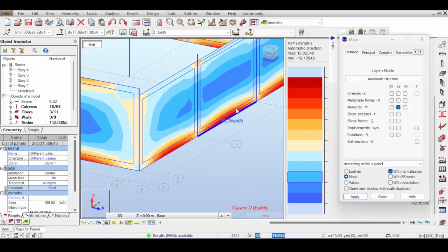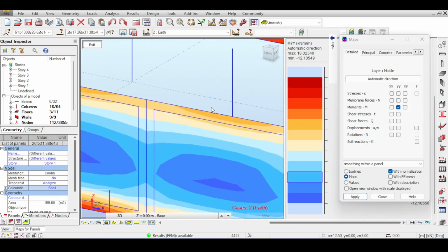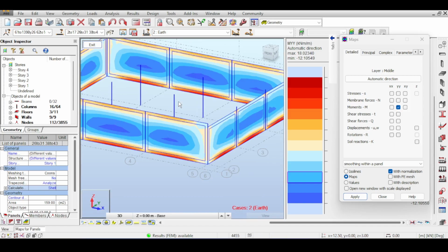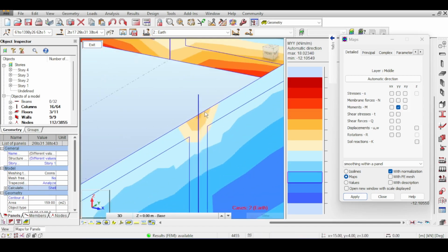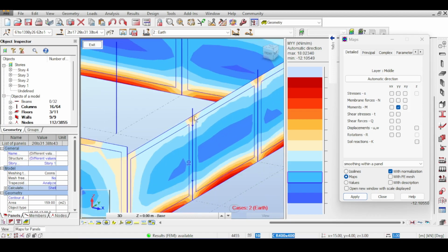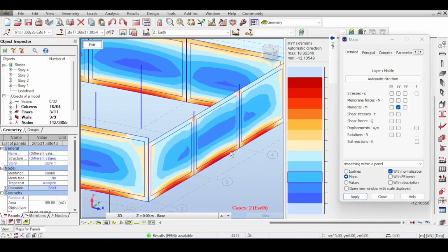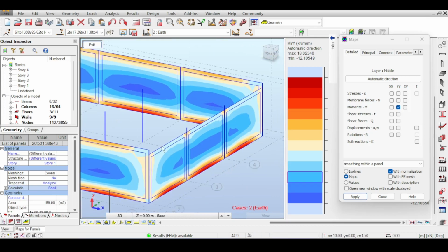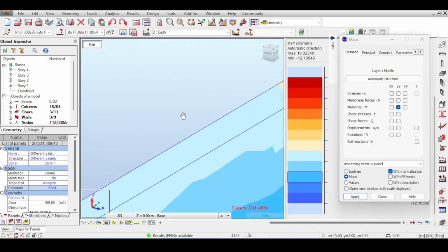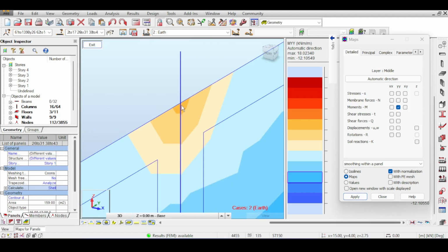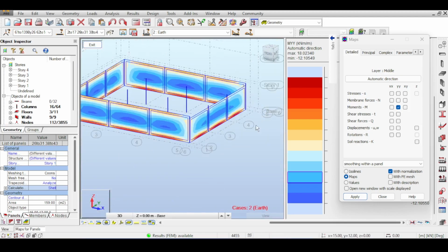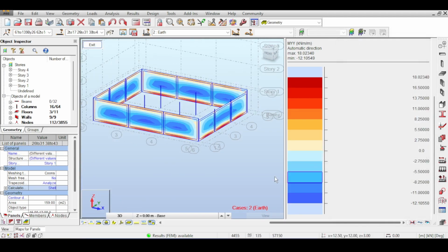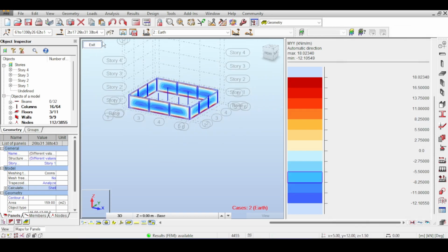You can see the stresses building in the base, and of course, here you have some stresses because you have a connection with the slab or the beam, whereas here you have zero stresses because there is no connection. I mean, stresses are moments, so you have moments here because it's connected, moments here because it's connected, and you have zero moments here because there is no connection. You have some moments here because there is indeed a connection with the column. So everything seems to be fine and seems to be making sense. However, you will be surprised when we design that thing. So let's go into the design of those things. Now, how do we design that?